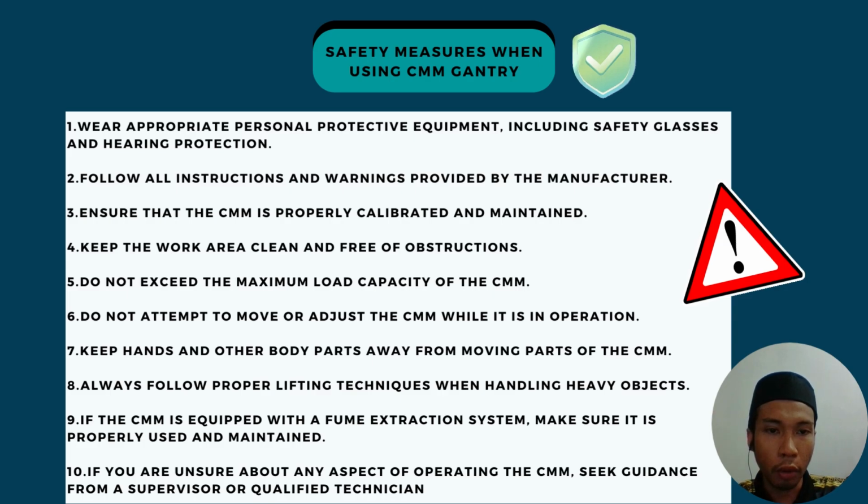And number 6, do not attempt to move or adjust the CMM while it's in operation. Number 7, keep hands and other body parts away from moving parts of the CMM. Number 8, always follow proper lifting techniques when handling heavy objects.